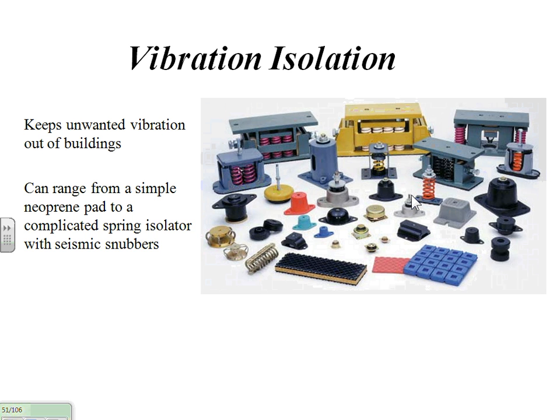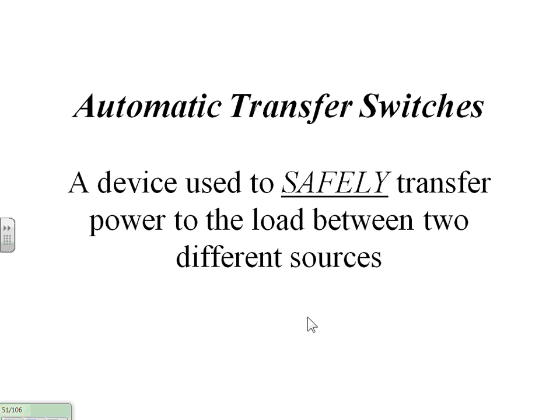In the smaller ones, 200, 100 kW, that kind of thing, and a lot of times we've even got them now up through 600 kW, we put this type of isolation between the generator set and the skid. So you can bolt it all the way down to the floor without any problems for maintenance and stuff, and critters that might get in there.